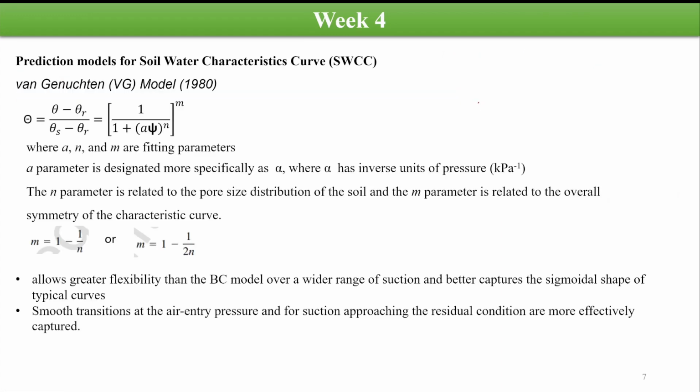The question says that an infiltration experiment was conducted in the horizontal sandy soil column shown in figure 9.5. So this is the horizontal sandy soil column, and the cross-section area of the column is provided as 100 centimeter square. The cumulative infiltration volume after 20 minutes of testing was determined as 200 centimeter cube. So we need to predict the infiltration rate and cumulative infiltration at 1 hour and 6 hours, right?